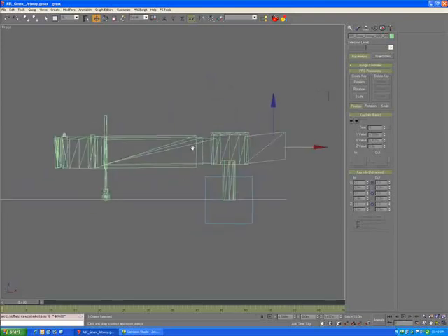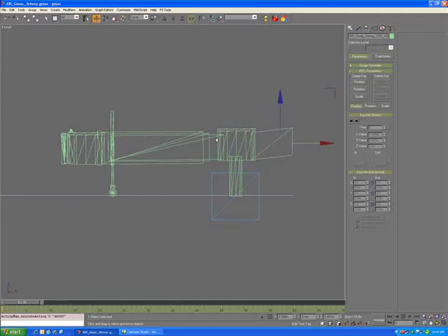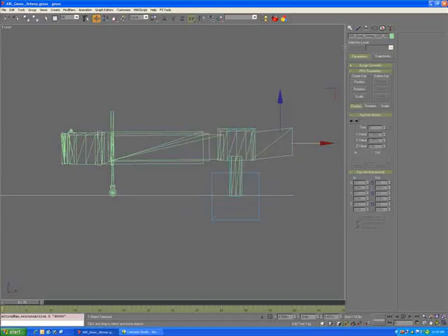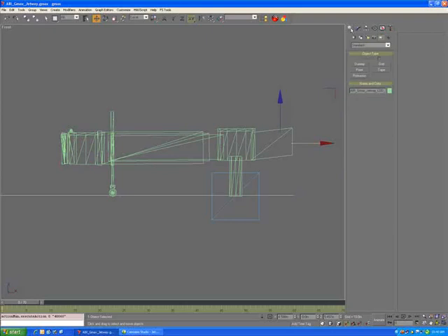So the first thing that needs to happen is you need to create the bone structure for this Jetway. In order to create the bone structure, I will turn on the 3D snap toggle down here, and then I will set the snap toggle to pivot. The reason you do that is so that you can align the bones to the pivots. I've already predefined all of my pivots correctly, you can see, so they all pivot appropriately.